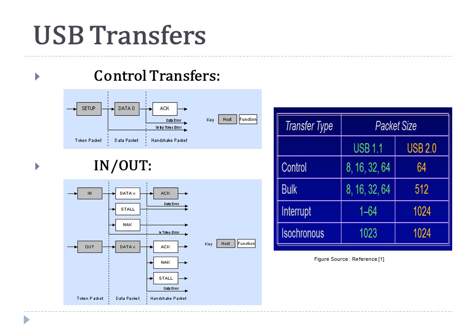So here is an example of a control transfer which uses the setup packet to identify that it is a control transfer, and control transfers are always initiated from the host. Actually, any transfer in USB is initiated from the host, and then it sends the data, which is whether it has to program certain functionality in the device, and the device on receipt of the data sends the acknowledgement. So if there is some error, the device doesn't send the acknowledgement, and the host times out and retries the transfer.